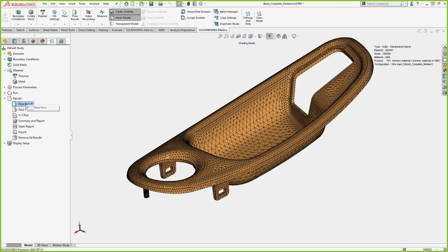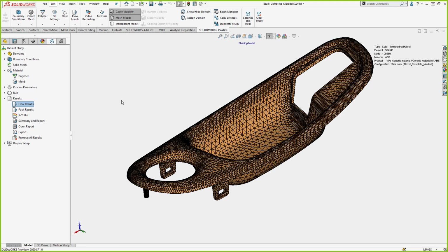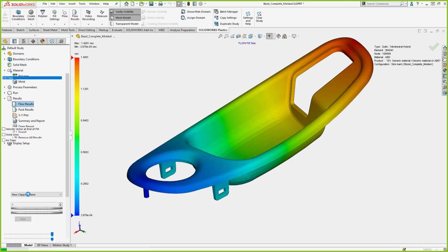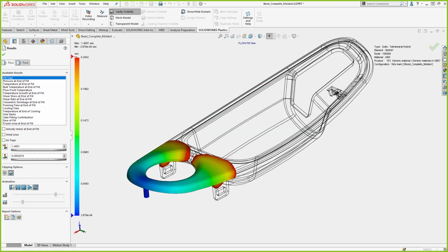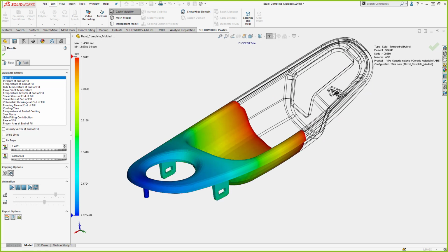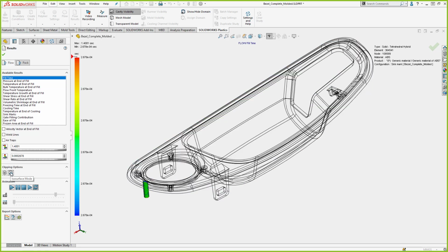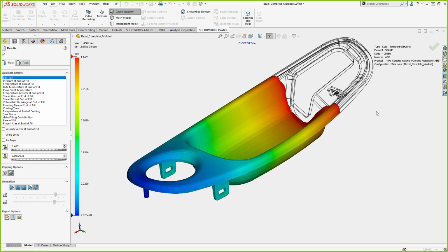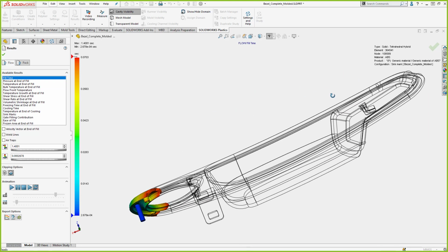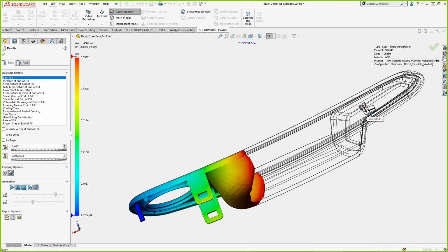So let's go in and look at the flow results on this model, and we're going to concentrate on looking at a couple of different items in here. Fill time is always an important one. This is also where you can actually look at areas and watch the filling of the material, the animation going through the part. It's got this ISO surface mode with a solid mesh going on. You can actually see the materials flowing through the part and around certain areas, and how it fills in different areas, where the last places to fill are, and all of that.